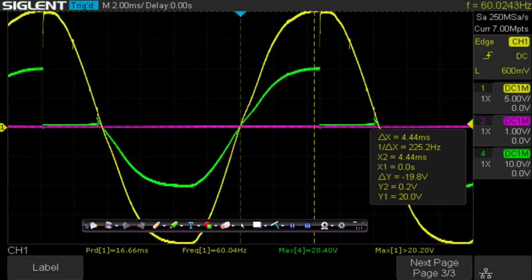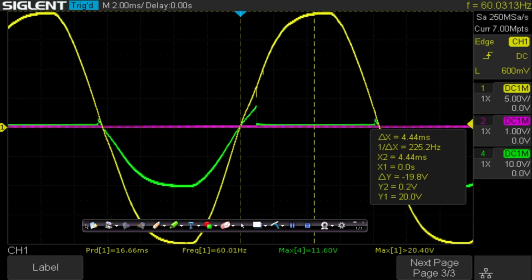And as you notice, as I adjust P1, don't worry about those little spiky things there. A little bit of filtering would take care of those. It is just built on a breadboard. See if I turn that down, the minimum position here, that little green peak there, that's the minimum firing angle, right? So notice how the zero crossings are aligned.